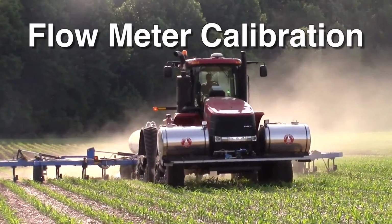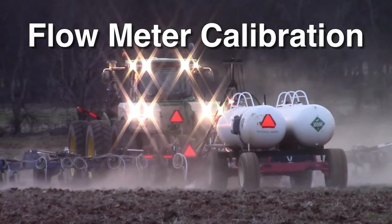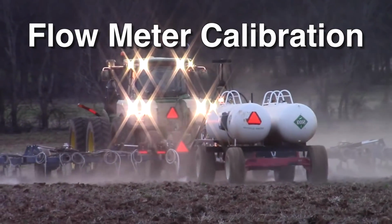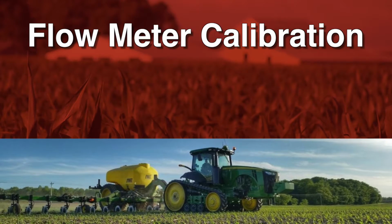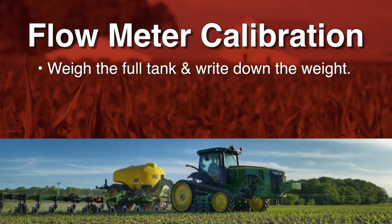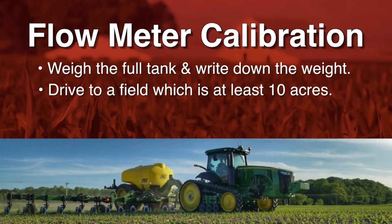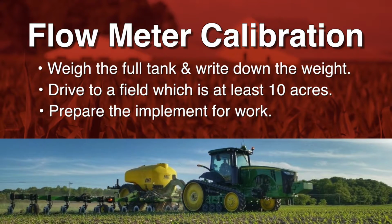Calibration must be performed during normal field work. This means that you can only calibrate the flow meter once the other system parameters have been configured. Follow these steps for flow meter calibration. Weigh the full tank and write down the weight. Drive to a field which is at least 10 acres in size. Prepare the implement for work.